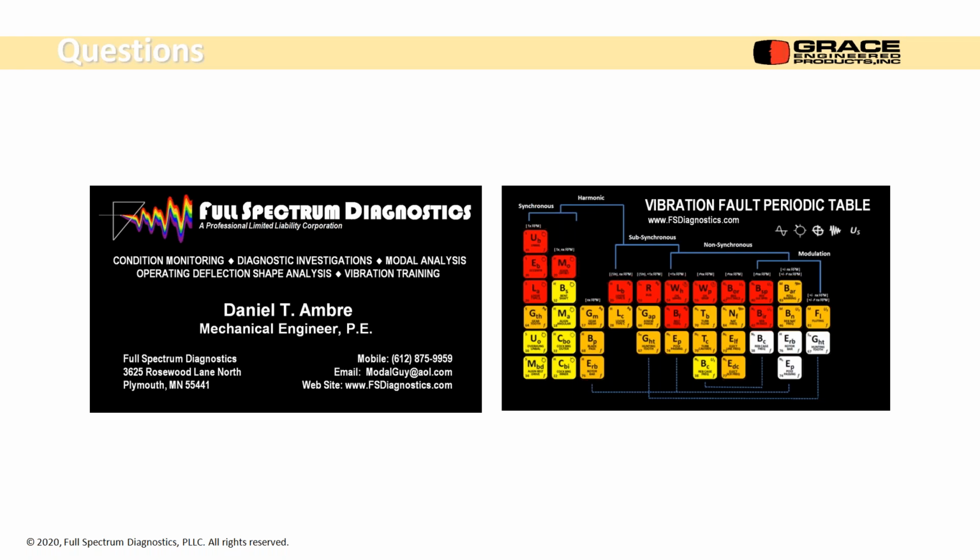So it tells you how the shaft is actually moving. It's light years more sensitive than a housing measurement on an oil film bearing. So with the probes, you're looking right at the shaft, you know that there's 6 mils of vibration, 6/1000ths of an inch, something like that. Whereas if you're on the housing, you might not detect anything across that barrier. Okay. It's just the animal it is.